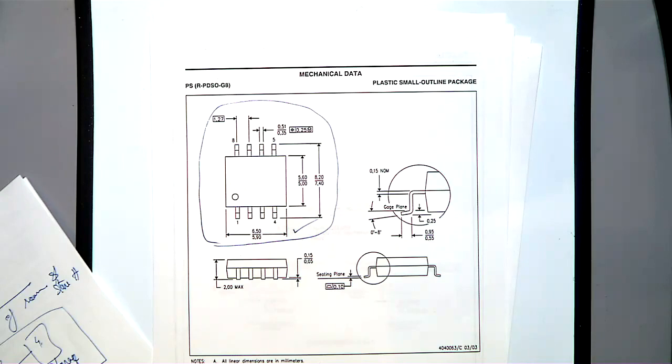LTspice also you can't take for granted, because you can simulate only if the code is available for a particular amplifier. If you don't have the code available, you will need to write the code for LTspice. You don't know that one? Because most of the time you go to the library, pick an IC and then simulate. But then that code is available. If you don't have the code, you have to write it. But in our case, you don't have to write any code in LTspice, because we are using amplifiers from the library.